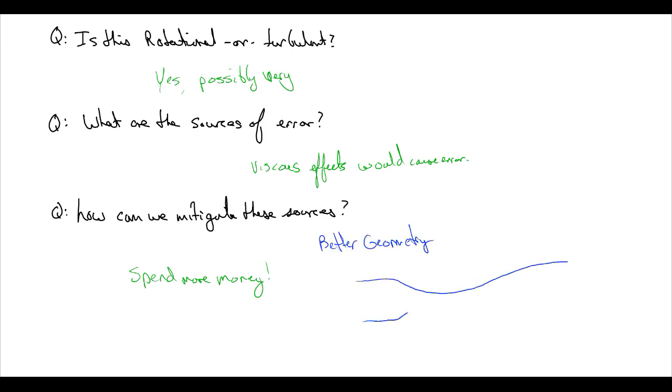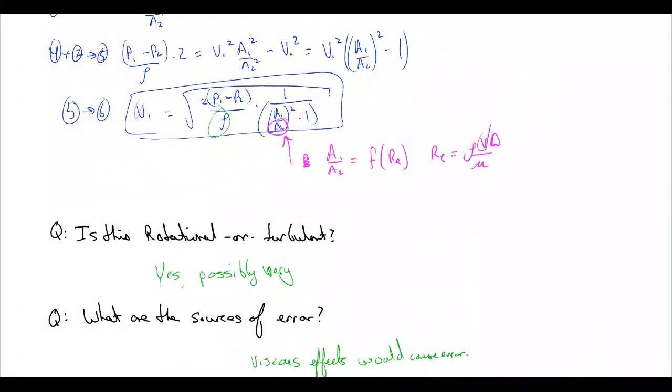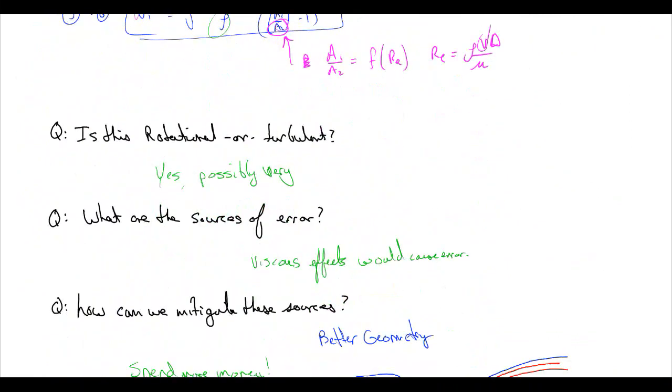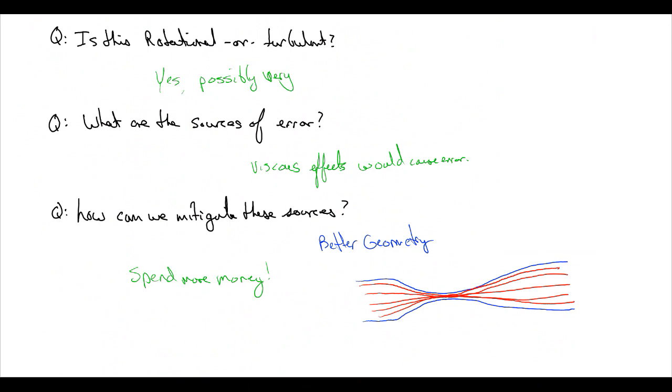So we can construct what we call a Venturi Meter, which has a relatively fast constriction and then a slow expansion afterwards. If we draw the streamlines for this, it's specifically created so that we don't get separation, right? We don't have any 90-degree bends that the flow has to go around, so it doesn't separate, and it doesn't create these vortices and these eddies that really generate a lot of viscous losses. So it's one, more efficient. Two, we know the different areas.